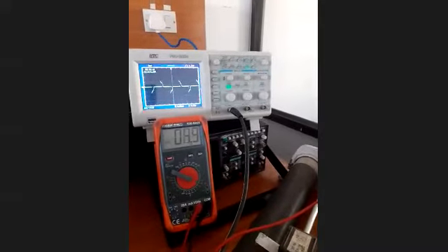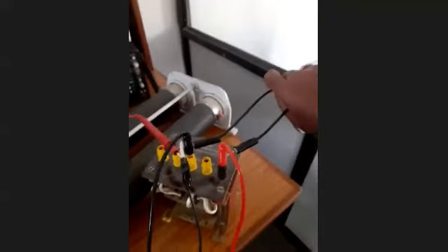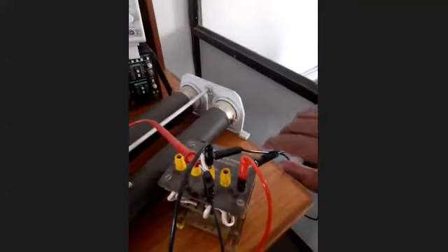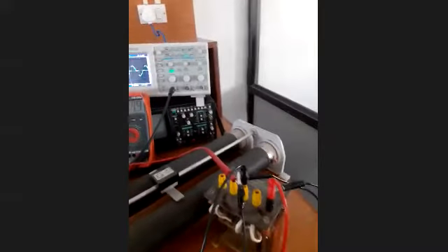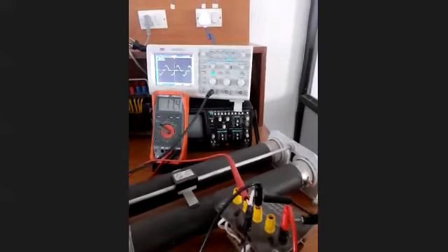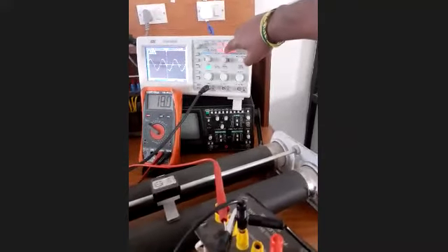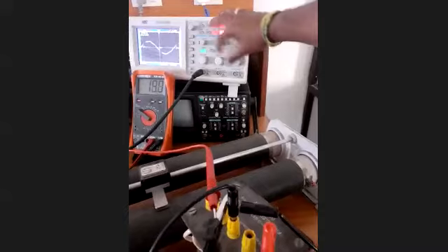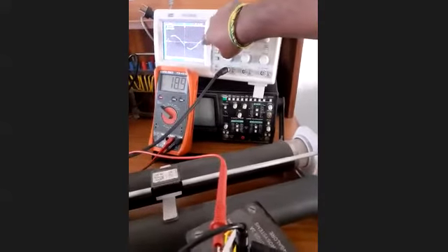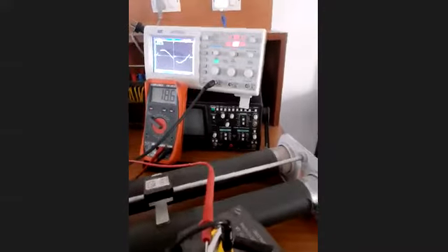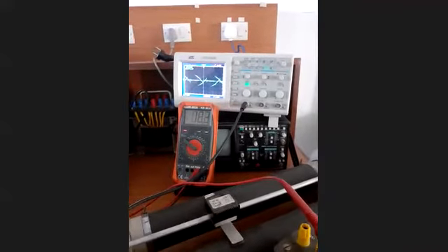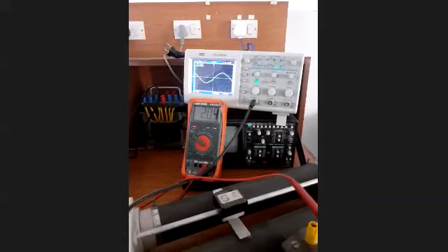The same thing you can achieve for the resistive and inductive load, where here you can see I have short circuited these two terminals. So even though I have connected R and L, they are in series. Due to this short circuit, there is no effect of inductance. Right now, if I remove this particular terminal, you can see there is an effect. There is a peak in the voltages, right? So this peak you can observe, and you can even vary that area. Now I can see different values of firing angle alpha, right?